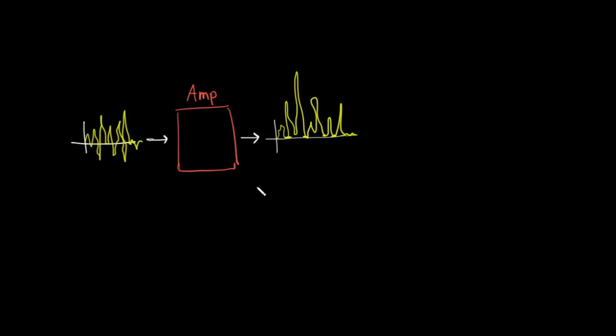No negative part of the signal will be allowed by the amplifier to pass to the output. This is for speech processing applications. This is a very real problem, because the speech signal that you generated contained both positive parts and negative parts, right? Both the positive and negative parts contain information about your speech.